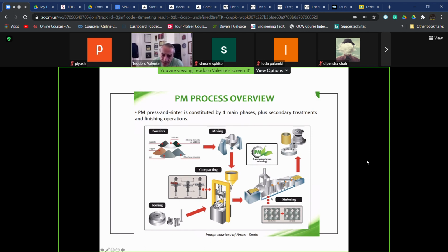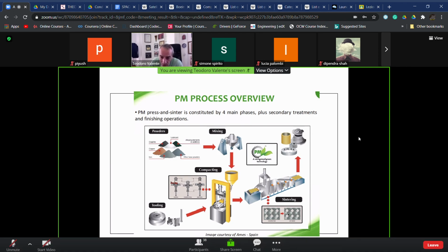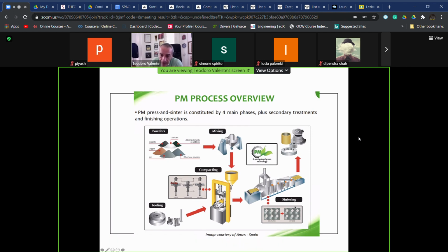And it is in this phase, in the phase of high temperature presence, eventually assisted by a mechanical force, that is by pressure, that the single powders which have been mixed or which are alloyed powders start to develop the 3D network by sintering, by solid state diffusion, after controlling the processing parameters, which depend on the final results we want to obtain.